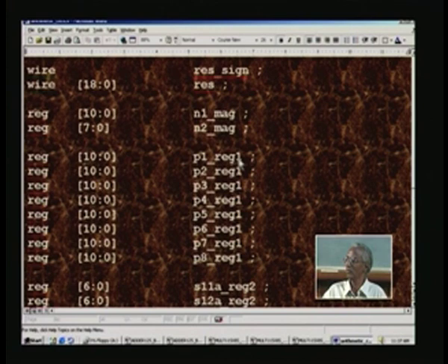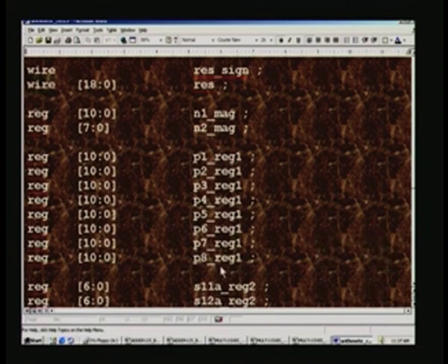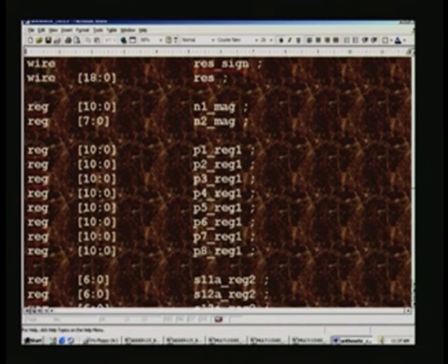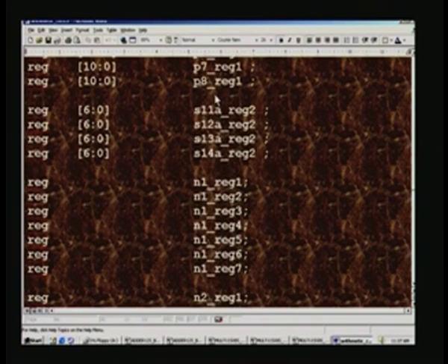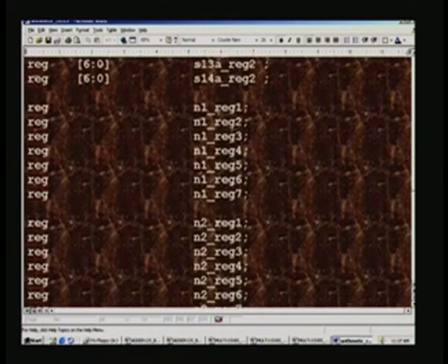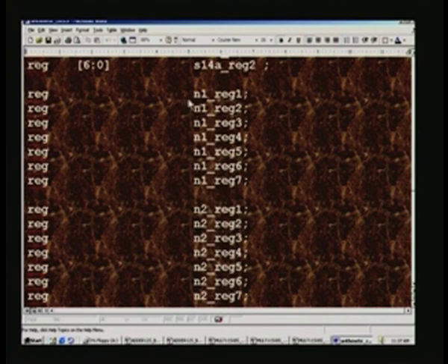For example, for clock 1, any registering you do for partial products, we give another extra reg1, which is the nomenclature adopted here. Similarly, for other pipeline stages, when clock 2 strikes we will have intermediate results in reg2 and so on. We also need to propagate the numbers sometimes, so that is what we do here.